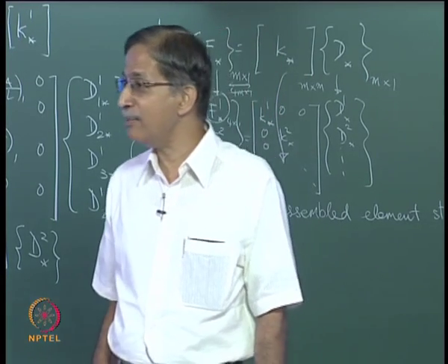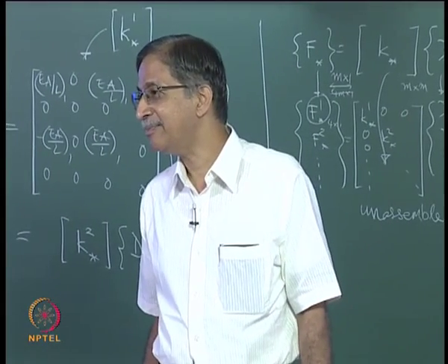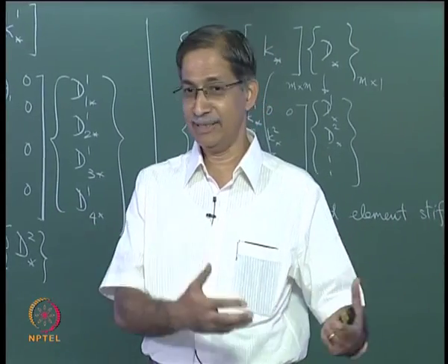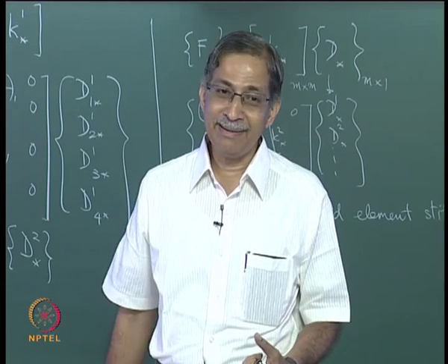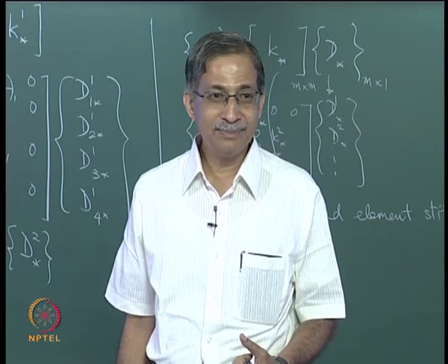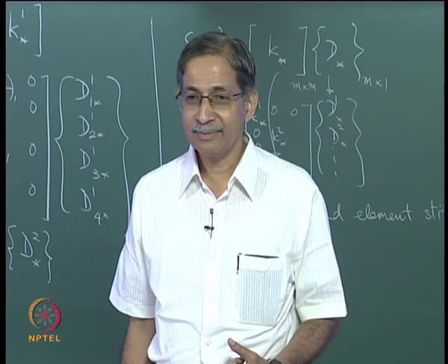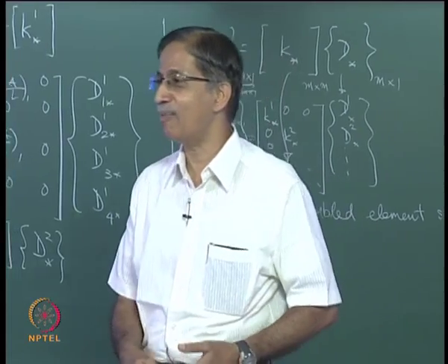Does it mean there is no element flexibility matrix? Because we have studied that the flexibility matrix is the inverse of the stiffness matrix. But clearly inverse is not possible. So what is wrong or what is right? Why physically, why is it not possible?